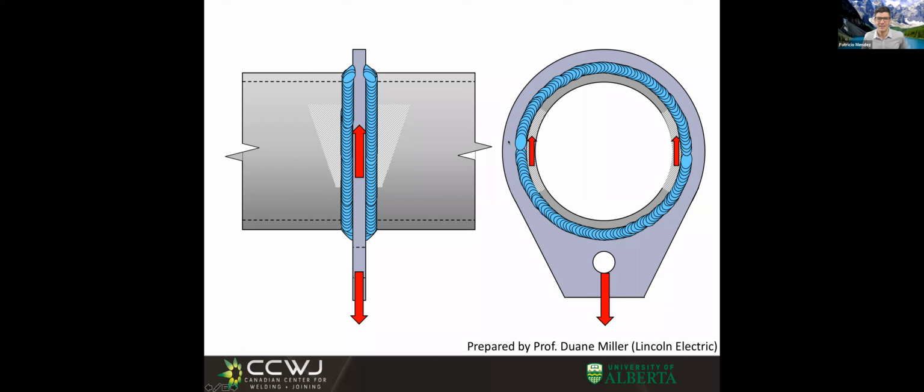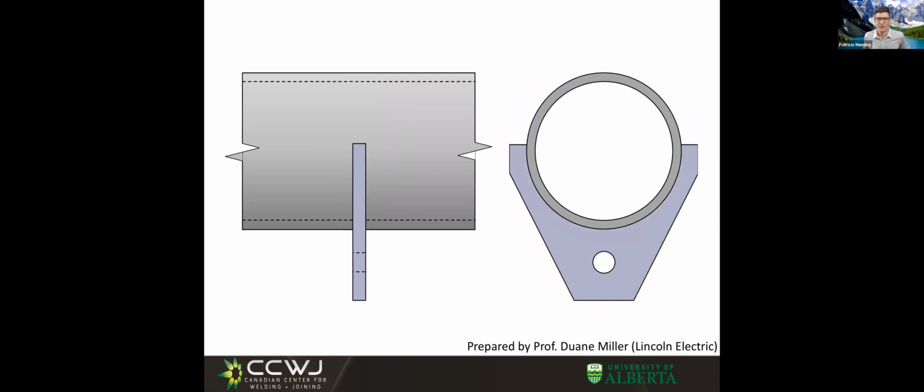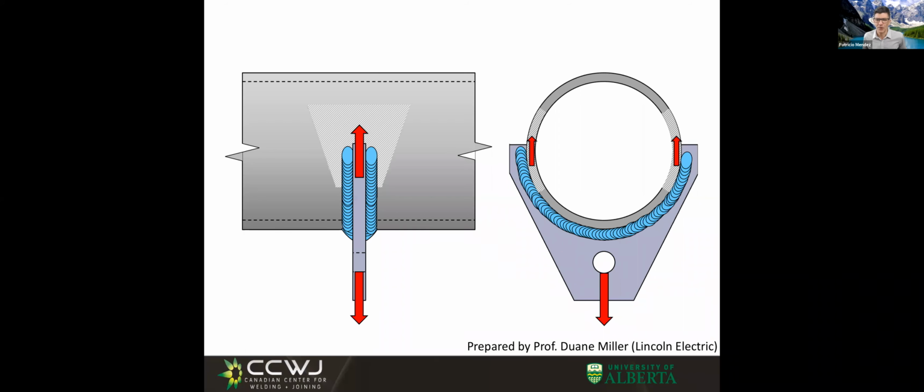In this case, that is a single plate. That would be hard to thread. Maybe we should make two halves there. But look at this. Here we have another possibility that is much the same. It's similar to this one, the stiffener ring that went all the way around. This one goes only up to the stiff sections. And what I was trying to mention before, all this part here that is against the compliant part, it doesn't take that much load. If we wish, we can take it out.